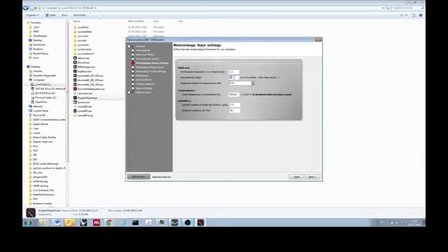If you want to have the wind from the west, for example, we just press 270. We'll just set it as an eastern wind. You have to bear in mind that this is according to your model and not the true north.